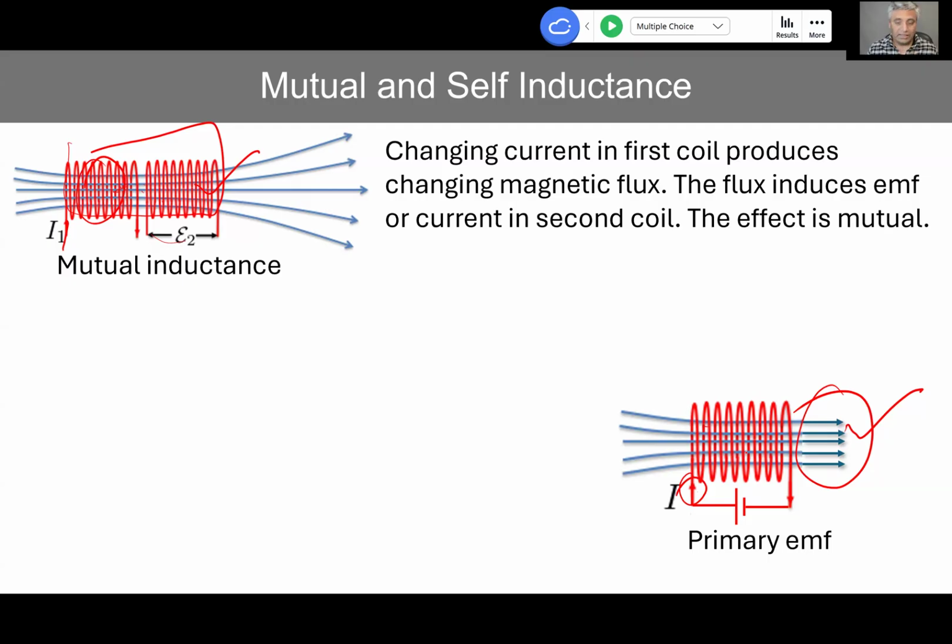What we are interested in is that when you turn the switch on, current goes from 0 to maximum, meaning flux goes from 0 to maximum as well. So there is changing flux. Now, to oppose that change, this being a coil, it is going to induce a current or EMF in such a way that the new, induced flux is opposing it. And that's what these green lines are. Those are the induced flux; these are the original.